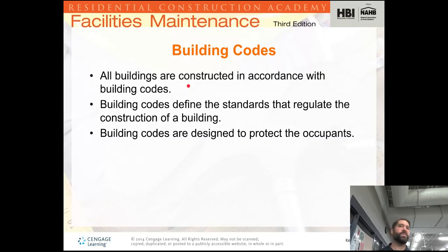So, for example, if you're going to frame out a wall and you decide to frame it on 18-inch centers when the drawing clearly indicates it should be 16-inch centers, guess what? Not good. Chances of you having to add more wood or even rip it out increase. And who wants to do rework? Not me. So do it right the first time. Don't try to cut corners. Make sure you adhere to these guidelines.